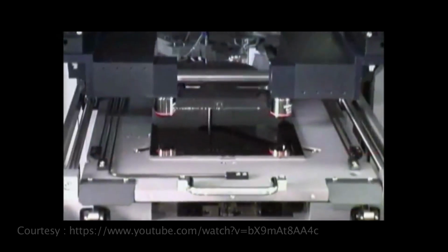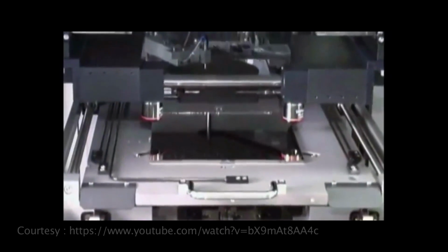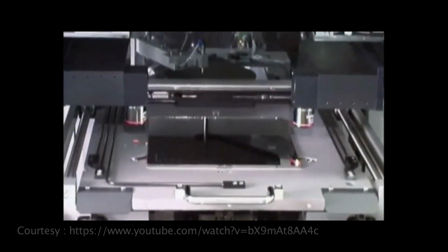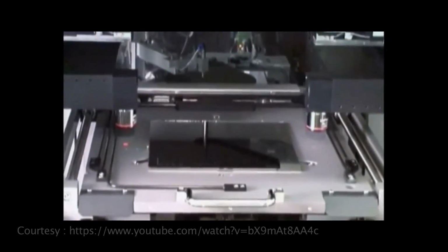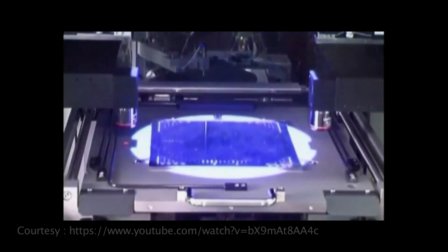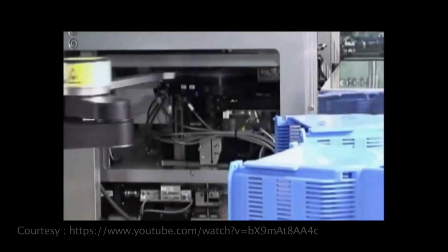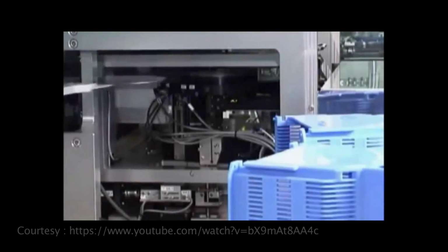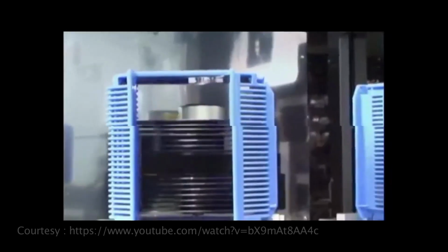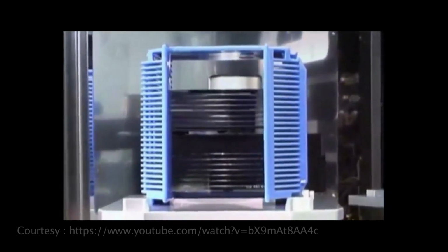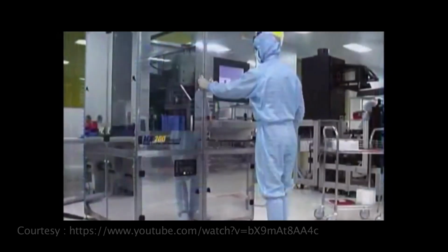In thin resists, it achieves a resolution of 3 microns in proximity mode and a sub-micron resolution in contact printing. A microscope for bottom-side alignment is optionally available. It can process substrates with thicknesses of up to 4 millimeters.